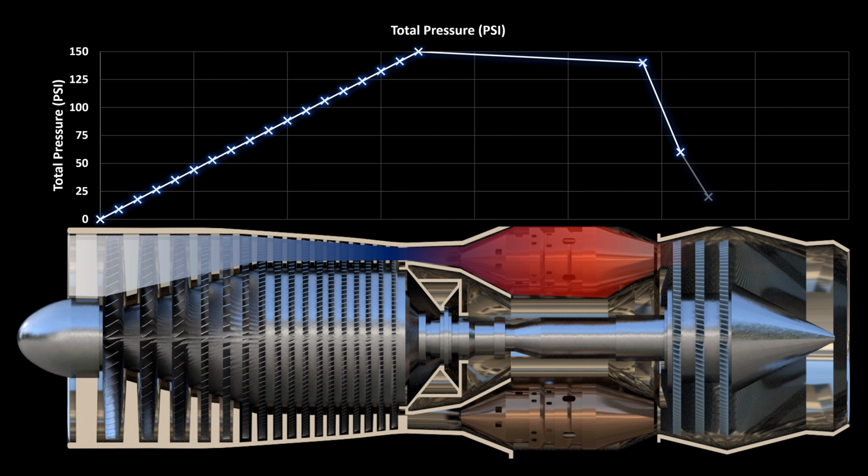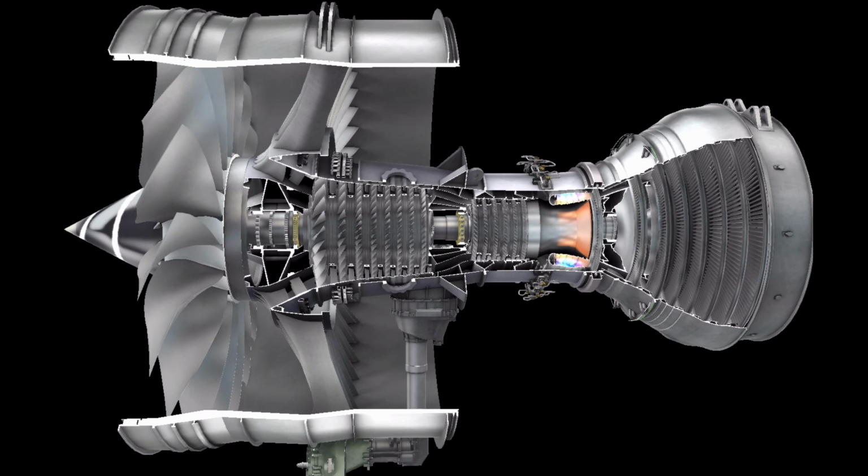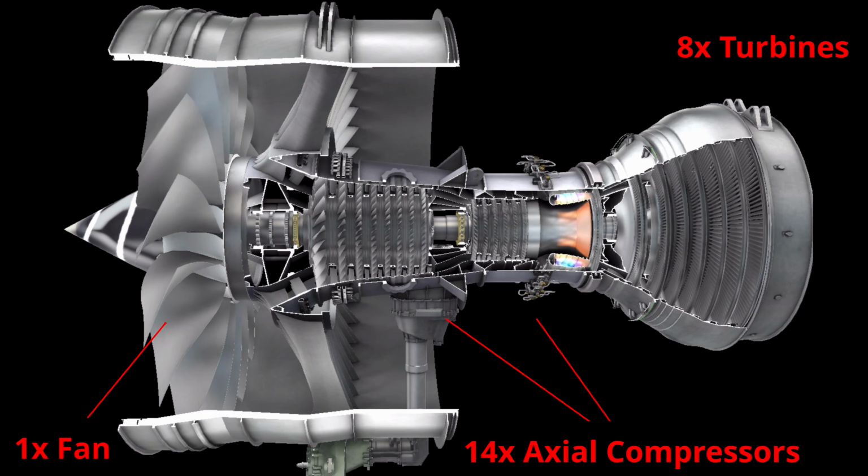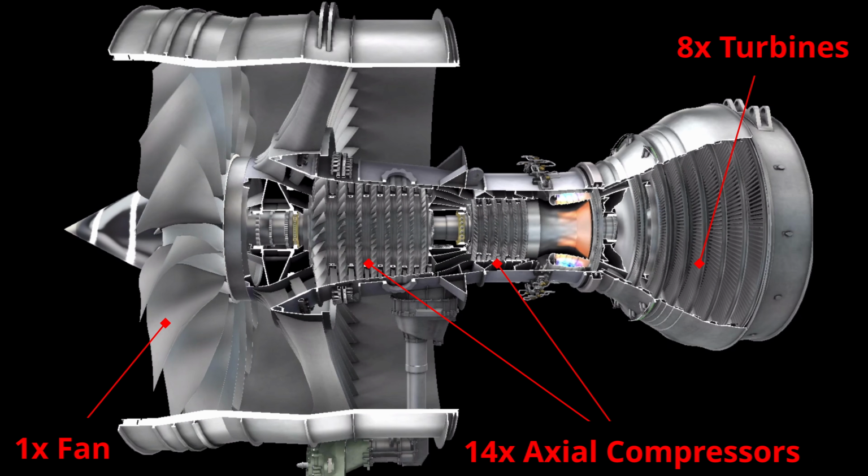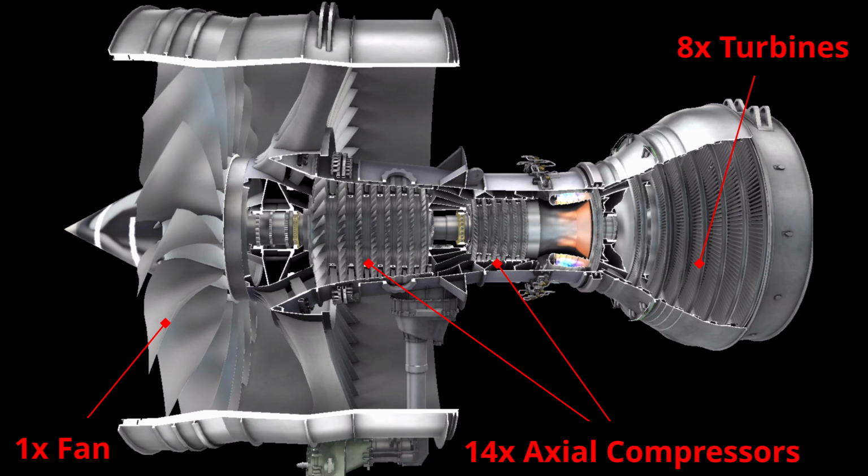In a turbine, the flow is moving in the natural direction of decreasing pressure, with no consequence to flow separation. Therefore, we can extract much more power from a single turbine stage. For efficient engines which operate with high pressure ratios, we typically need many stages of compressors.